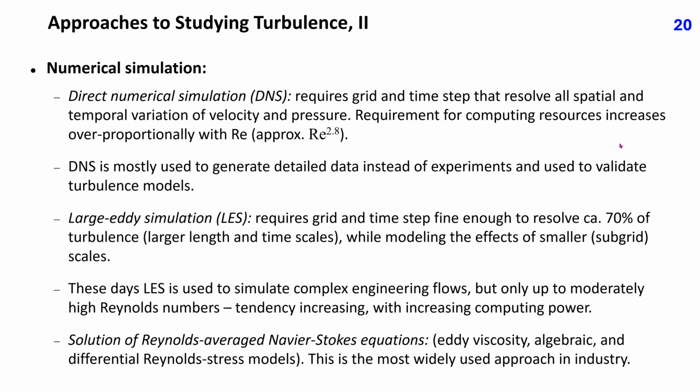Large eddy simulation, or LES, requires grids and time steps fine enough to resolve circa 70% of turbulence, that is, the largest length and time scales, while modeling the effects of smaller, called subgrid scales. These days, LES is used to simulate complex engineering flows, but only up to moderately high Reynolds numbers. The range of Reynolds numbers for which LES is usable increases with increasing computing power. This approach will be described in Lecture 31.